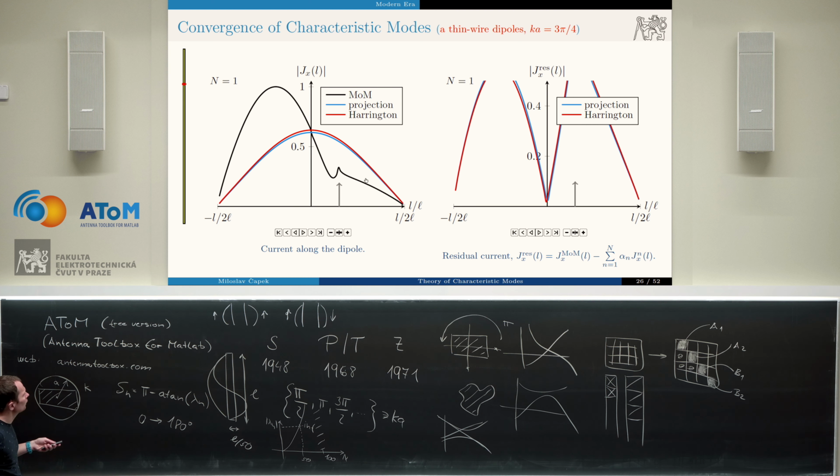And here, this is done on this figure for P_rad, which is the radiated power, and for W_sto, which is the stored energy. By the way, these two quantities together give a Q factor. That's why I use them here. So omega times stored energy over P_rad is the Q factor.